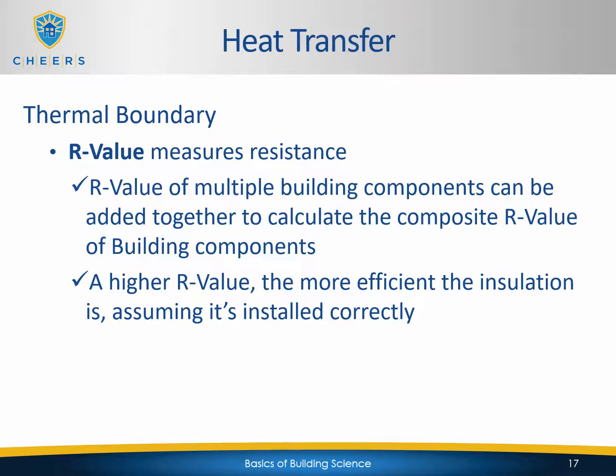And keep in mind that it measures the efficiency of the insulation assuming it's installed exactly by manufacturer's standards. So you could have a piece of insulation with an extremely high R value, but if it's installed improperly or very poorly, the actual R value of that insulation is going to be very diminished compared to what it was supposed to be.